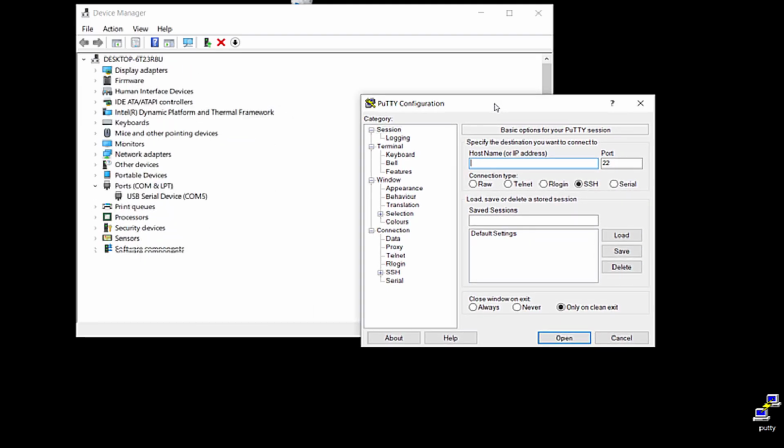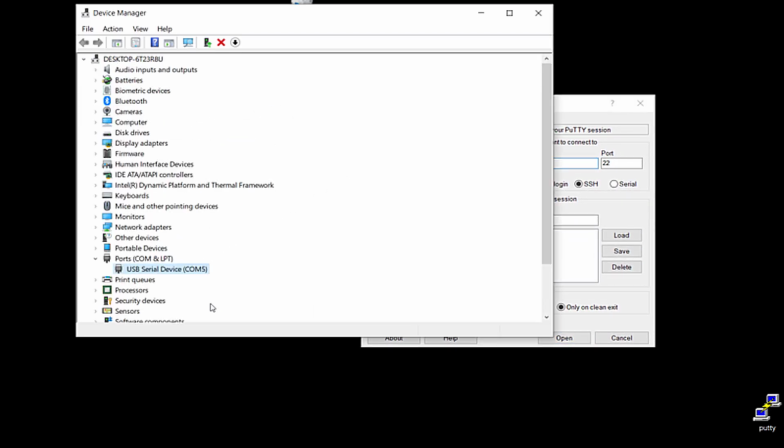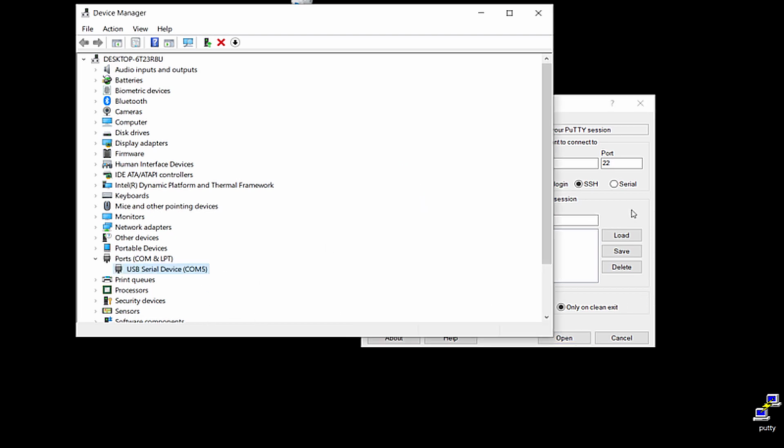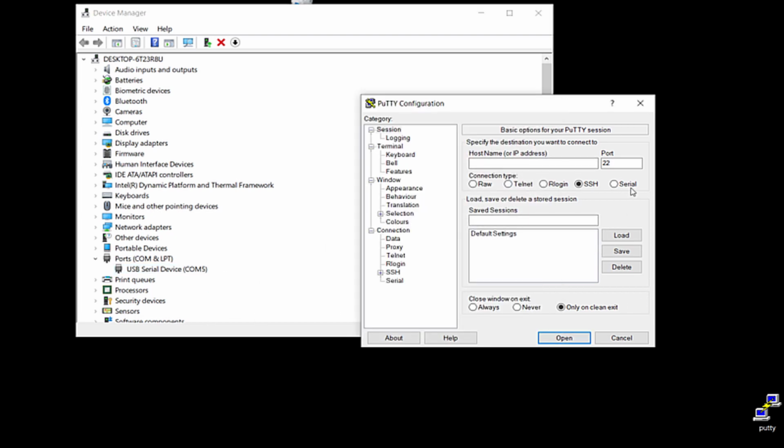So as a bonus, you can remove this Raspberry Pico actually from the Raspberry Pi right now. Because you have the file inside, then you can plug it into your computer, for example. You can find directly the port, the COM number, the port number here, the 5, and using, for example, another terminal emulator like PuTTY, and type the baud rate.